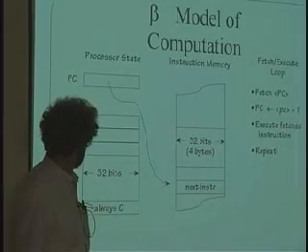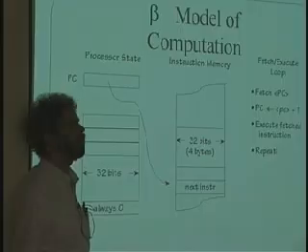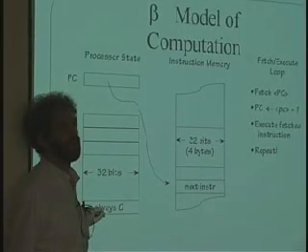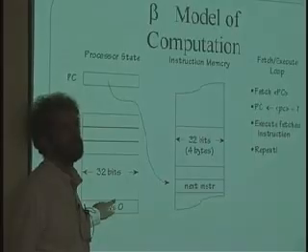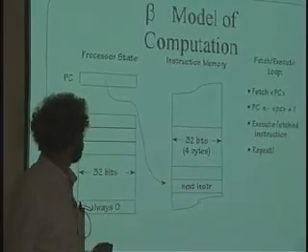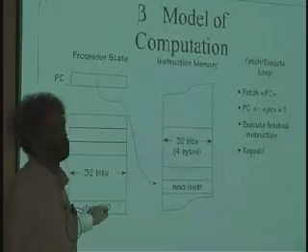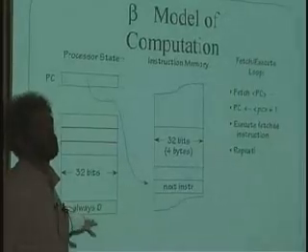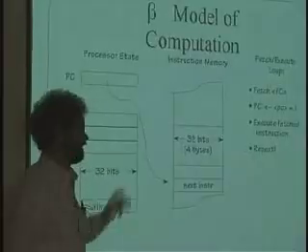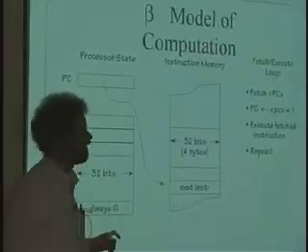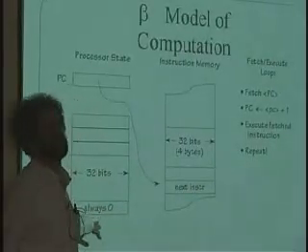So we're going to actually say that we're going to throw away one of the registers, and we're going to make it always 0. If I read register 31, the last one of these 32 registers, it will always be 0. What happens if I write it? Smoke comes out of the system, right? Conflict between zeros and ones? No, it just throws out the bits.